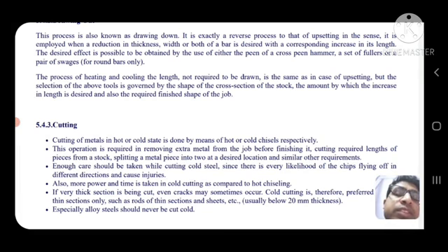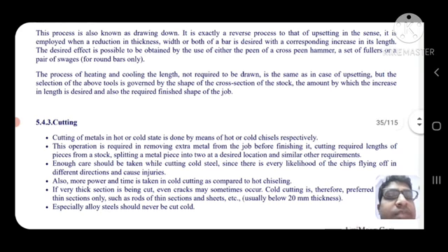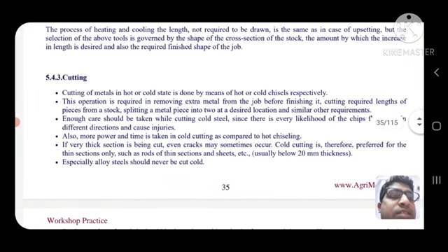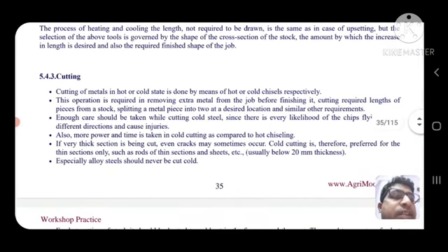The process of heating and cooling the length not required to be drawn is the same as in the case of upsetting, but the selection of the above tools is governed by the shape of the cross section of the stock. The amount by which the increase in length is desired also depends on the finished shape of the job.